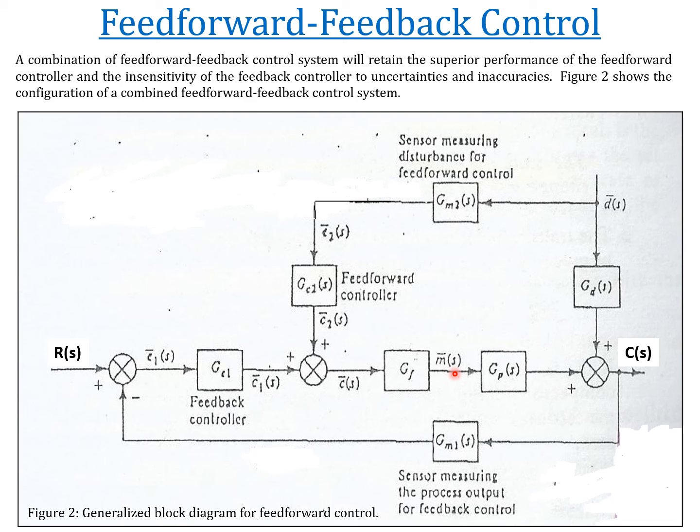The other thing is that it can be implemented by basically simple methods. Okay, if we use that practical feedforward controller, we just tune the gain. The alpha, beta, you just need the gain, tune the gain, and you can implement the feedforward control. So you can implement it on analog, on a hardware system without the computer part. But if you are using a very sophisticated model and the equation of the feedforward system is more complicated, you need to have a computer system, then you have to implement it in the computer.